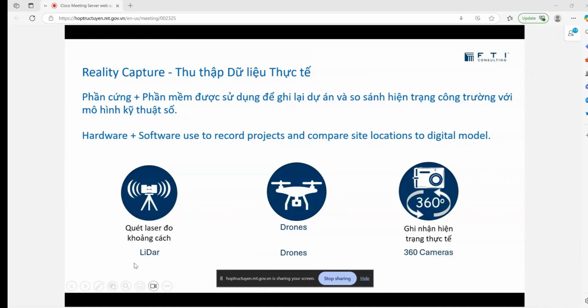You can use laser scanning for high density point clouds for high accuracy. This is important if you're trying to make sure that you've got headrooms for railway corridors under existing structures. If you don't need the accuracy, you can use drones. Drones can be, as in this example, propellers, or they can be fixed wings. Fixed wings will be more useful given the length of the alignment, so you can capture a lot more information.